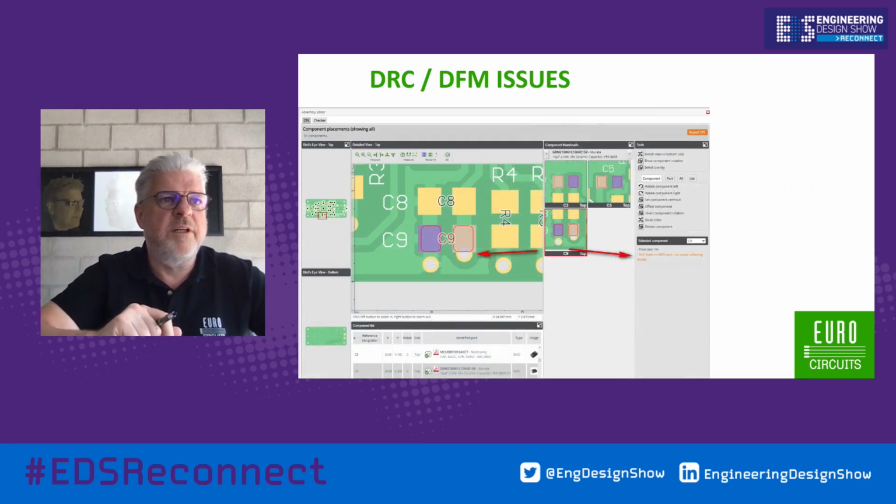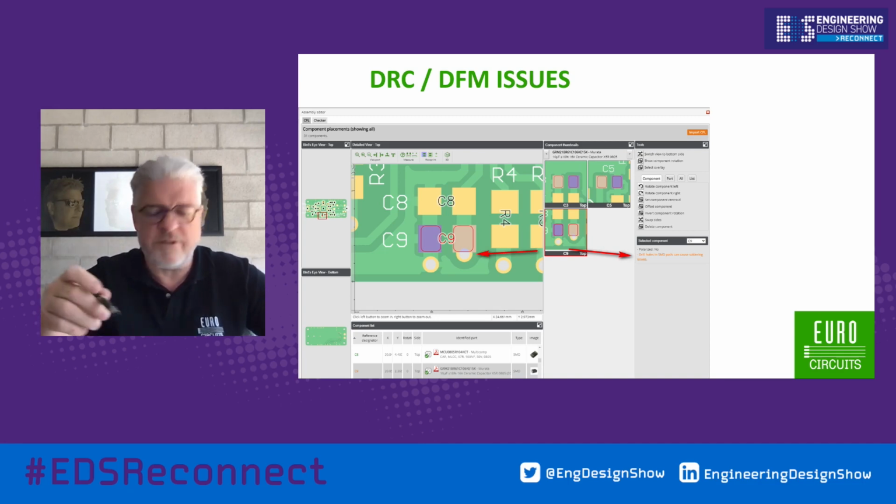In the next step, this is another typical thing that happens a lot, we check for a solder drain. Where you see the arrow, you have a via which is too close to a soldering pad. And what will happen is that the solder paste that you print for this pad will disappear into the via hole during soldering and will create a bad soldering connection.